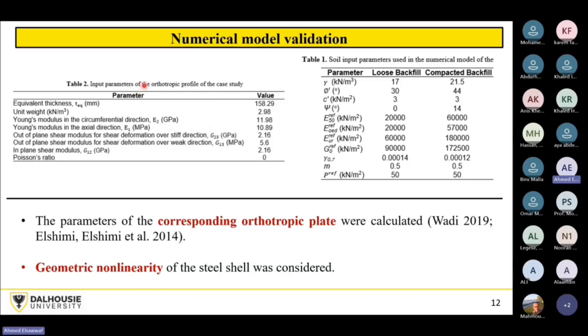For the corrugation profile, I told you that if you want to explicitly model the corrugation in Plaxis, it's doable, but it will take much time and lots of meshing problems may happen, specifically for large spans and large structures, and even for something we call bevel-ended treatments.